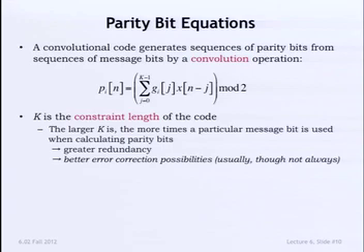The number k is referred to as the constraint length, and it's the maximum number of message bits involved when you look over all your parity expressions. So in this particular instance, k would be equal to 3. It's the maximum window of data that you're using in a non-trivial way to generate the bits. Here you're using up to 3 to generate this. Well, in this case also, you're using a window of 3 message bits. It happens that you're ignoring the one in the center. But the constraint length is the length of message that you're actually looking at.